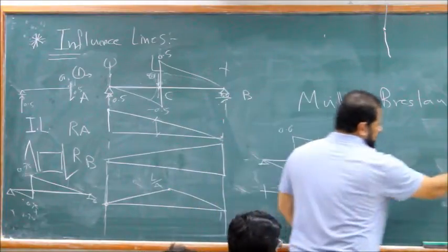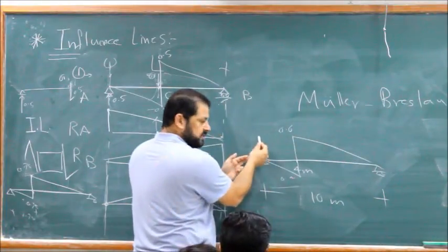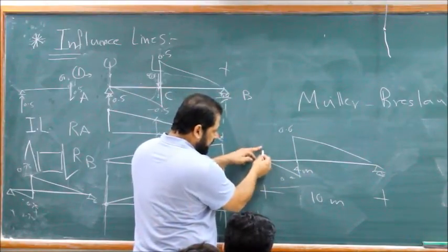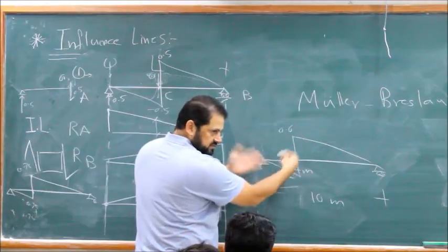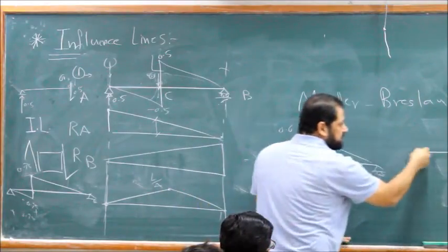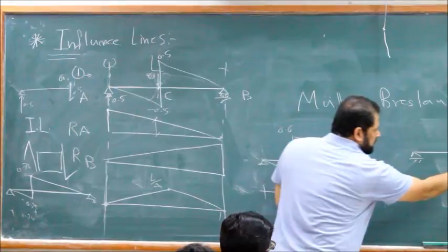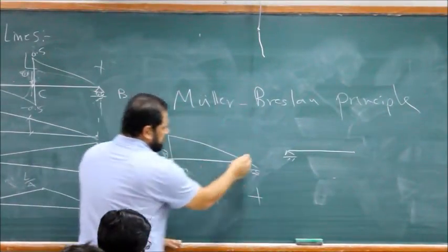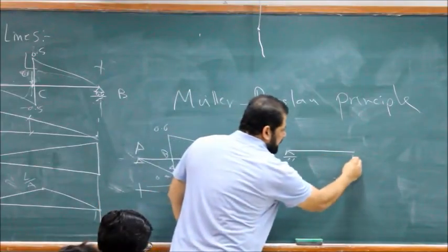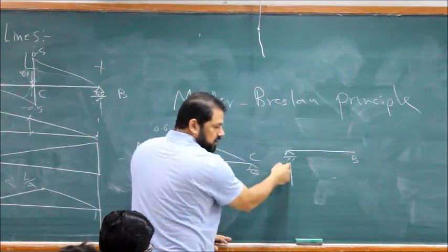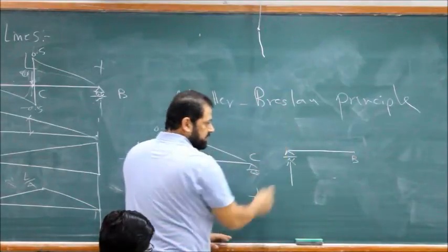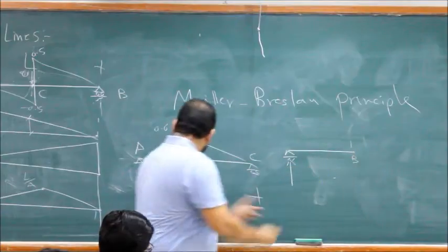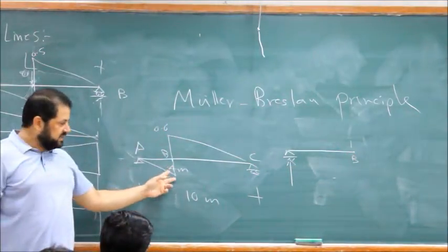How we did this is the following. At each location, you calculate the influence. When the unit load is here, the reaction is 1. When you take your cut, there is no shear. This is your cut, and this is the point. This is A, B, C, so that's your point B. Always the reaction is in the equation, always the reaction in the cut. When the unit load is here, before it crosses, see what's happening when it crosses? There is a jump of 1.